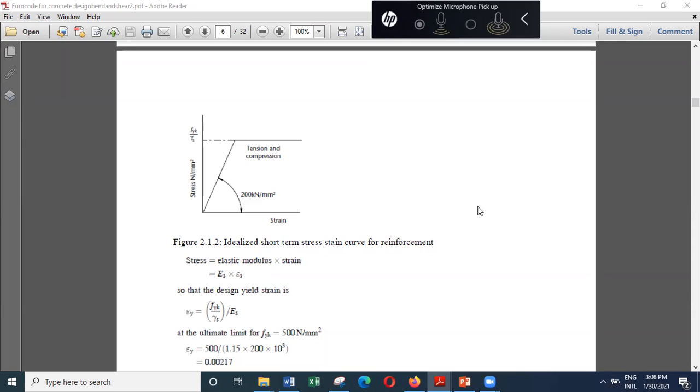And the way that is manufactured is, when the bars have just turned out, when it is red hot, water is sprayed on the bar so that the outer surface becomes cooler immediately. That process work hardens the outer surface. And then this bar is allowed to cool gradually so that the inner portion of the bar will be at a lower strength than the outer crust.